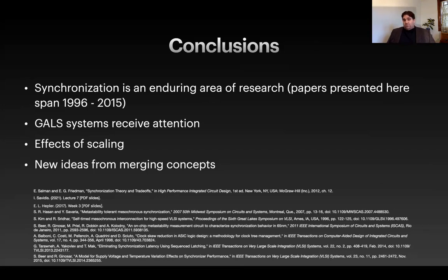And finally, I thought it was interesting that a lot of these papers merged concepts that, at least in my mind, were discrete from one another. So for example, and this is just by virtue of a GALS system, you're creating a new system from a system that's synchronous and a system that is asynchronous or self-timed. So you're merging two concepts to give you a new benefit. The same thing with the paper that was discussing the generating of clocks. You can generate your clocks in the front end, you can generate your clocks in the back end, but what if we can merge these ideas? So again, it's the concept of merging to create something even better.